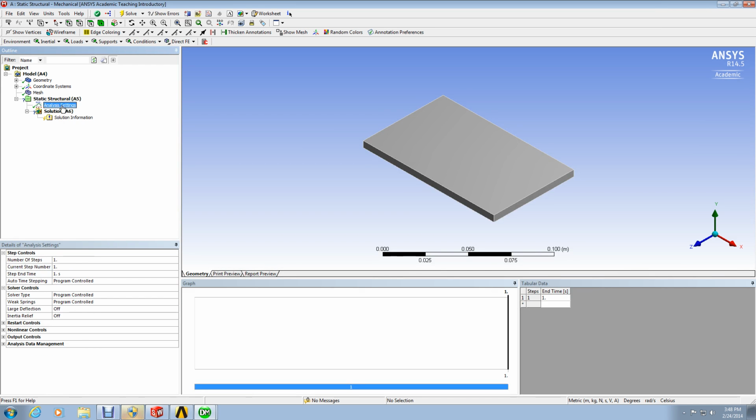Okay, analysis settings. You have to set up the analysis here. We have to set the supports first. So we hit supports. If you notice here, look at simply supported. You can't really choose it. It's available, but you can't choose it, because the system is not a 2D system. If it's a surface, as you're going to see, we can select it right away. But here you just use fixed support on an edge.